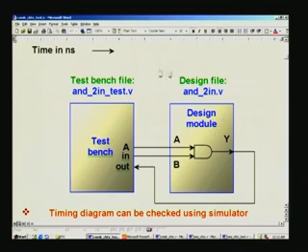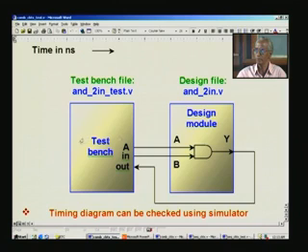Although you can put both in a single file and then call the stimulus, as you see in general textbooks, I do not follow this. If our ultimate goal is to design VLSI systems, the length of the code will be enormous, and if you take this approach of stimulus, you will run into difficulties, because you can't make out what you are doing when you are indulging in so many signals.